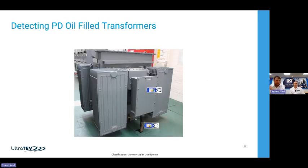So where would you look for PD? Nice and simple on a full transformer. Most things from a PD point of view call back to the cables. And we're able to therefore take measurements on the cable itself and on the cable termination. So the cable box on the outside metalwork using the TEV, the contact transient earth voltage capacitive sensor in the top of the device.